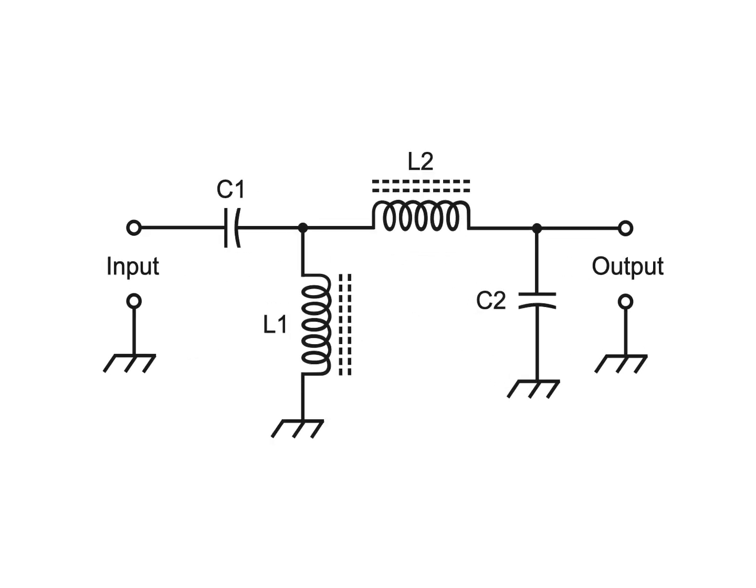This shows a more complicated LC circuit that consists of two filters, one after the other. The first filter, made up of capacitor C1 and inductor L1, is the same high-pass filter design as we just saw. The second LC combination, made up of inductor L2 and capacitor C2, forms a low-pass filter. It works in the opposite manner from a high-pass filter, letting signals through more easily as the frequency goes down. When we follow a high-pass filter with a low-pass filter, and if we choose the cutoff frequencies, or transition points, so that the high-pass filter's cutoff frequency lies below the low-pass filter's cutoff frequency, we can get a bandpass filter in which a signal can get through easily only when its frequency lies between the two cutoffs.